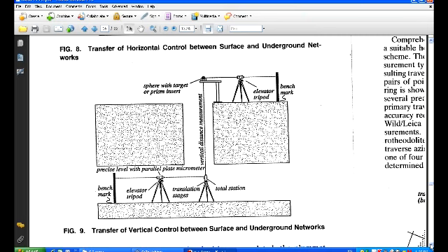In this particular case with a super collider, it was almost the same as first order vertical transfer, so that means it's sub-millimeter. That means also then that the total station has to be substantially supported, as does the sphere at the top of the shaft. This is a very simplified diagram. It's quite a process in the actuality to provide all these different supports.